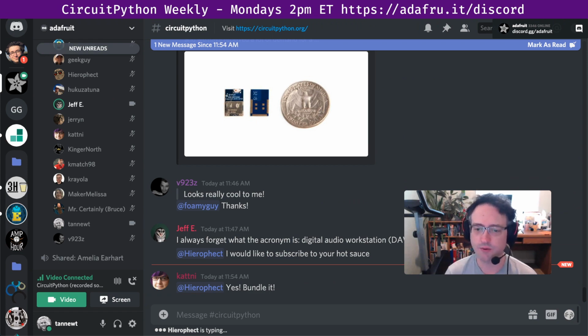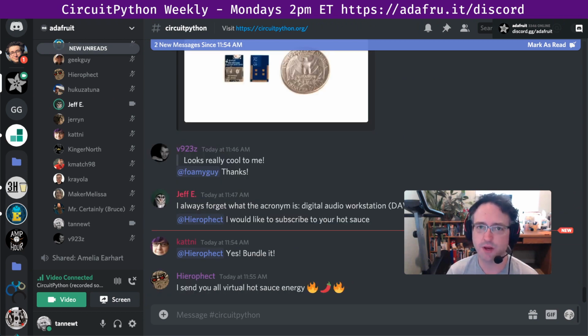This week, I will be working on the SDIO SD card interface on a SAMD51. I've got a Grand Central wired to a makeshift SD card breakout. And so far, it's just been writing boilerplate to move towards having a bus IO style object that encapsulates the bus, getting the actual pin management correct, instead of just skirting around that and ignoring it like I did on STM because we knew we had one defined port right there on the board.